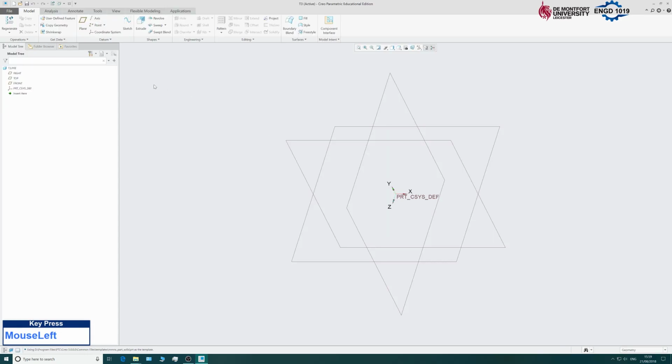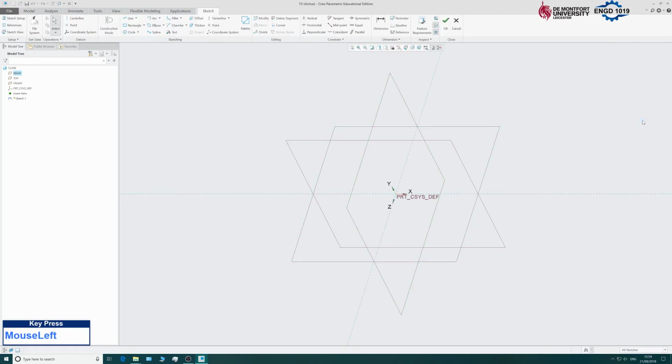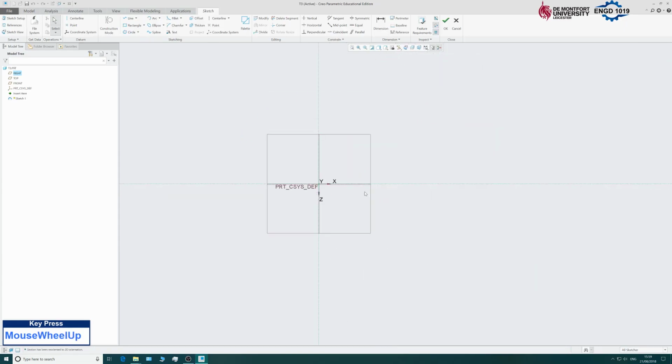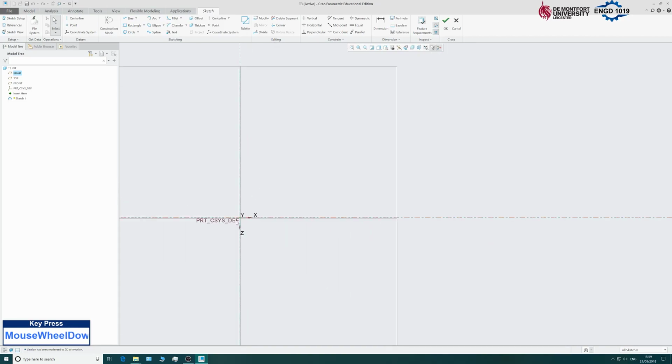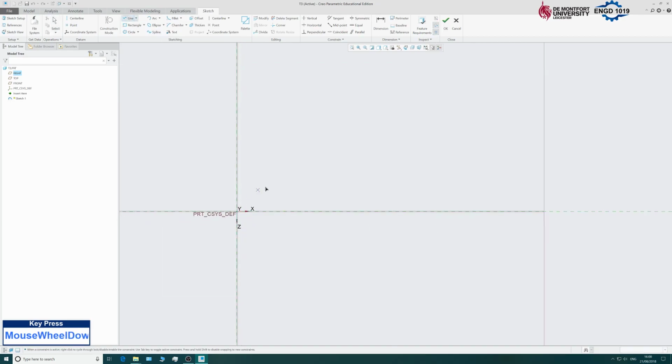Okay, so to use a revolve tool, we start in exactly the same way as we do with the extrude tool. So we start by generating a sketch. Okay, let's go to Sketch View. And so for this shape, I'm just going to put a general outline using the line tool, and then we can modify it to get the fine details that we require. So first of all, just use the line tool.